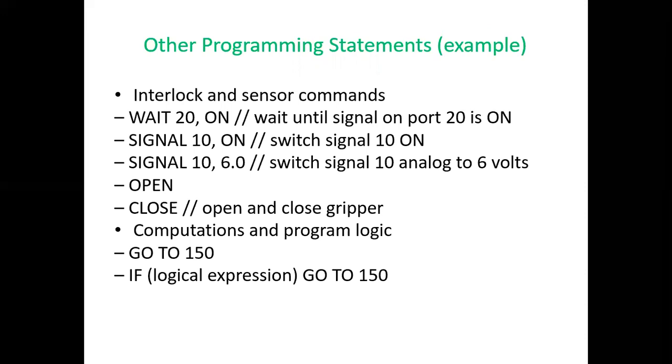SIGNAL 10 ON, that means switch 10 on. SIGNAL 10, 6 means switch signal 10 analog to 6 volts. Then OPEN and CLOSE, that is open and close the grippers. Then computations and program logic, then GOTO 150. So for a logical operation, IF logical expression GOTO 150.